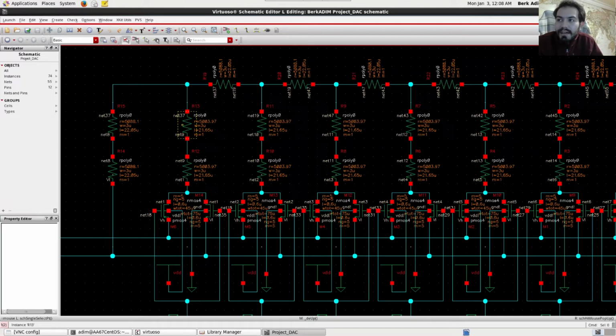For instance, we have a 4 volt range 8-bit DAC here, so we have 256 steps, and at every step we expect our output to move up 15 millivolts. So if you don't have good monotonicity, it might just move up 5 millivolts, or it might not move up at all, which is a big problem. If you choose larger resistances, you get more noise, but you actually get better monotonicity because the relative discrepancies between individual resistances are decreased.